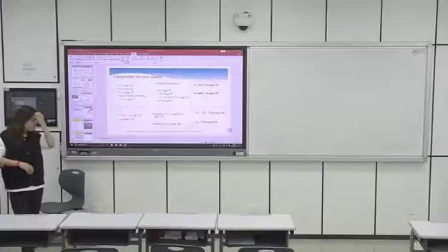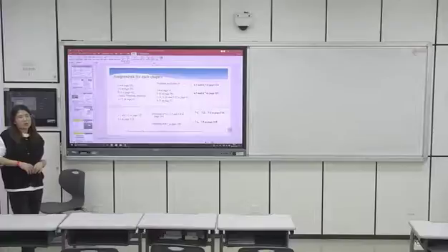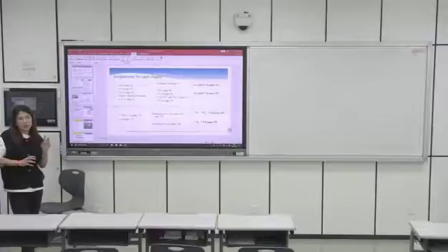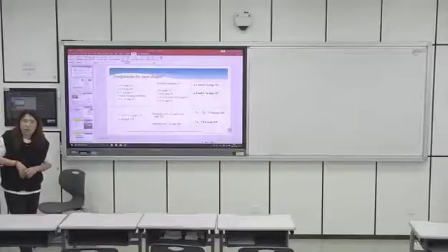So this causes some new parameters like the void ratio definition, right? And saturation degree, right? Void ratio is a volume relationship. It is the voids' volume divided by the solids' volume, right? This is the definition of void ratio, right? And we have a porosity n, right? There is a relationship between void ratio and porosity.